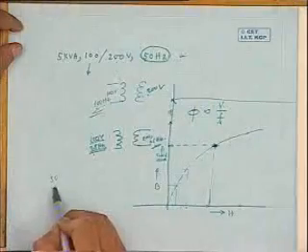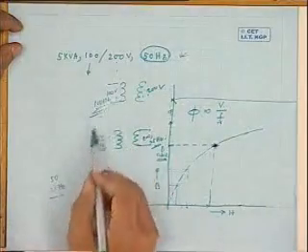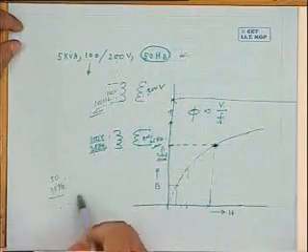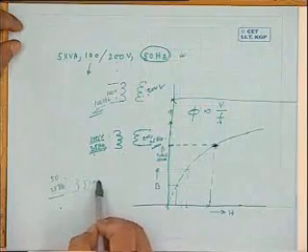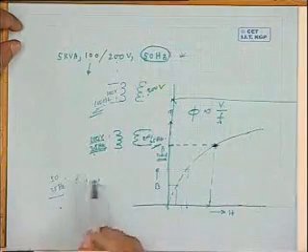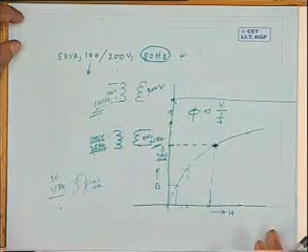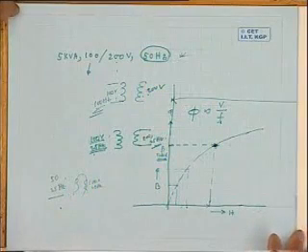However, at lower frequency you can operate it. Then what voltage should you apply? You then apply 50 volt 25 hertz. You can use this transformer, but apply to the 100 volt side 50 volt 25 hertz. It will act as a transformer, but on the secondary you will be getting 100 volt 25 hertz. Are you getting? Then the flux level in the core will remain the same.